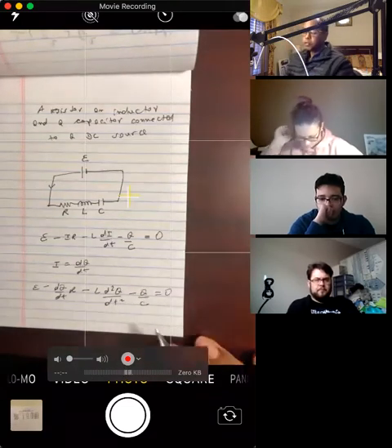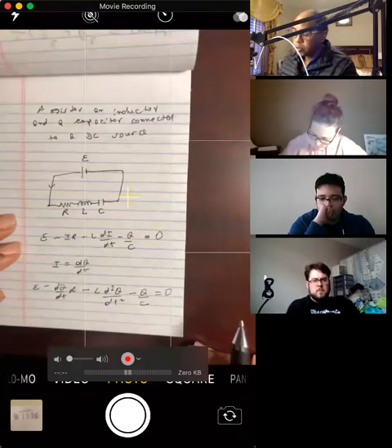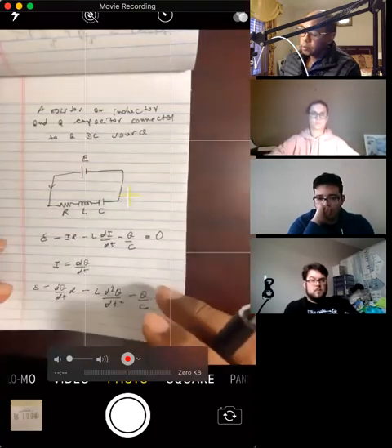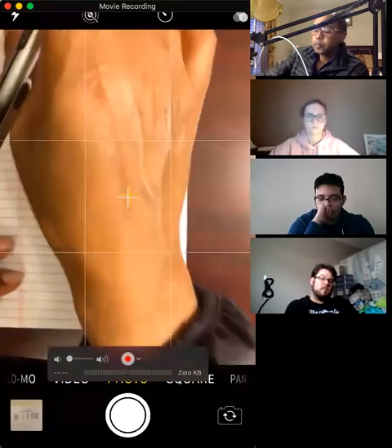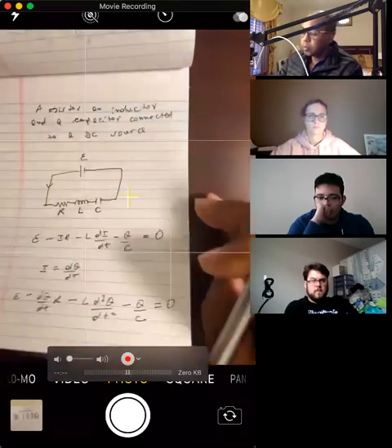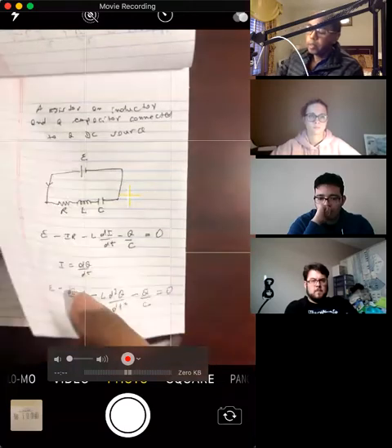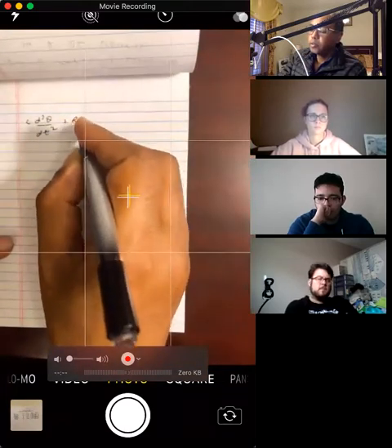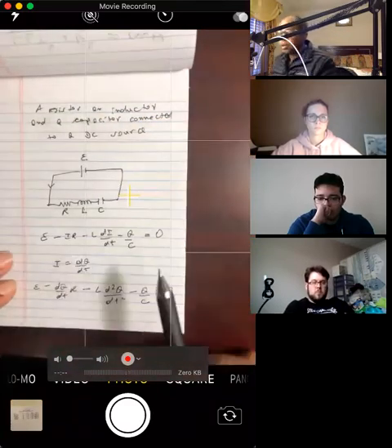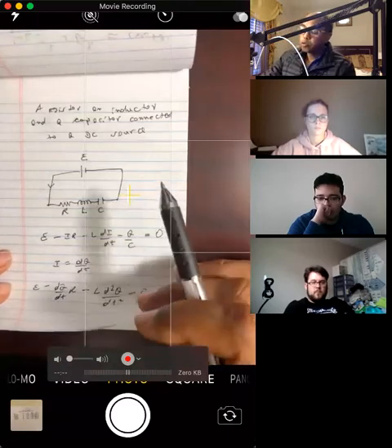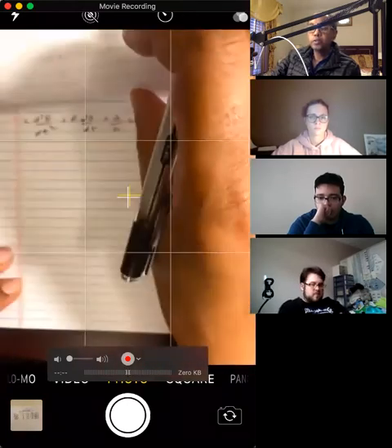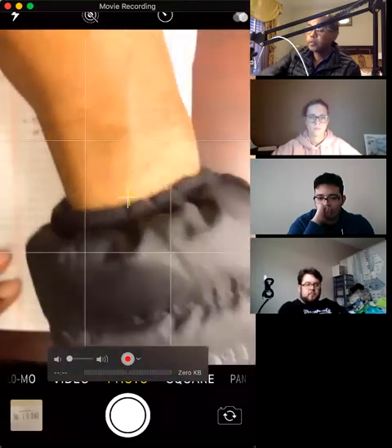Okay, so as you can see, we have a second order differential equation, but let's rearrange it. So we have L, let's put the second derivative first, d squared q by dt squared. I'm going to multiply the whole thing by negative, and then plus R times dq by dt. That is for the resistor over here. And then for this one, plus Q over C equals the EMF E, this one right here. So you've got E over here.